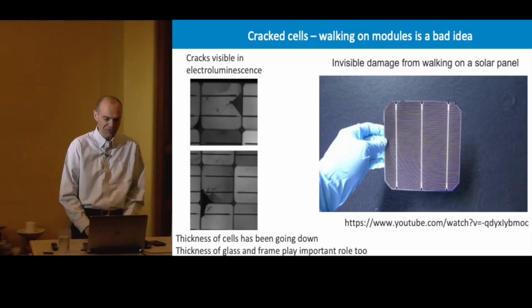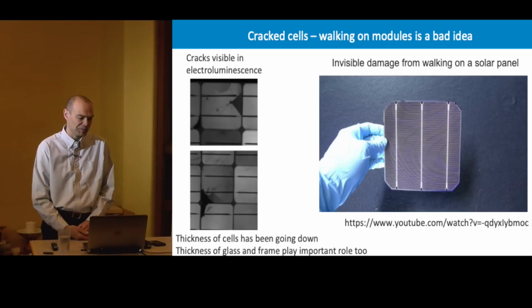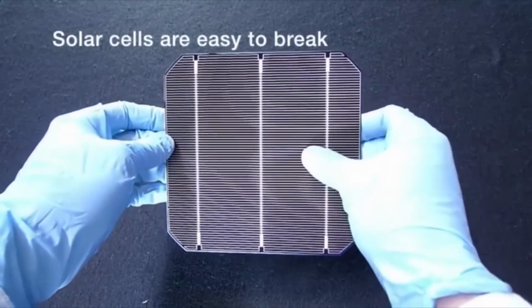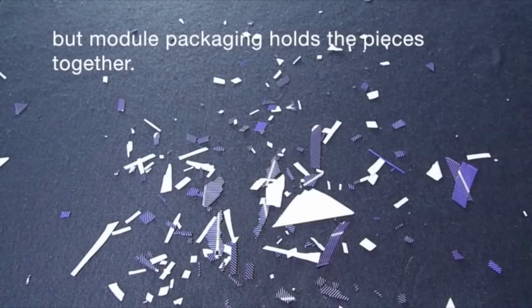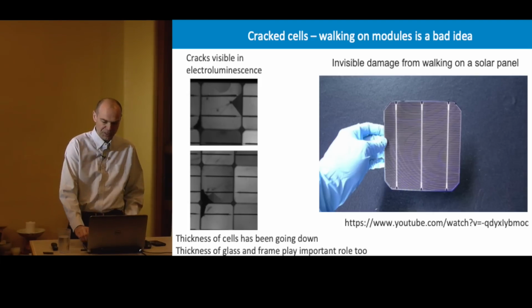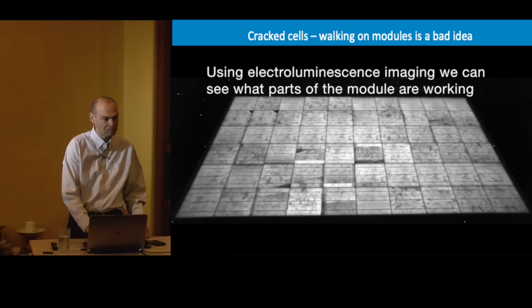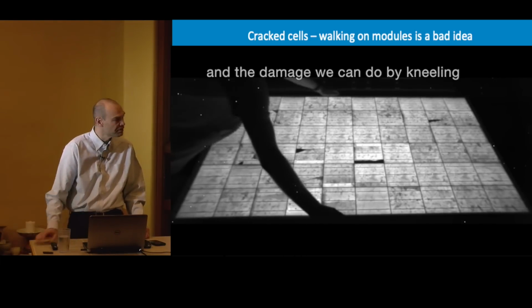They can also be caused by cracked cells. On the left are some images from a module where you see some cracked cells. They're seen by EL, electroluminescence. You send current through the module and look at the module in the near infrared. You can see these cracks. The thickness of cells has been going down. They actually lose thickness. Yes, yes.